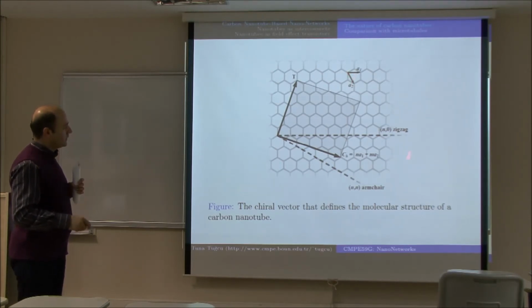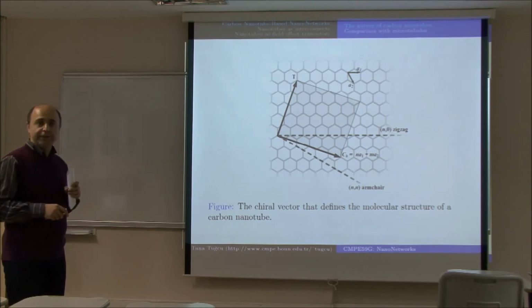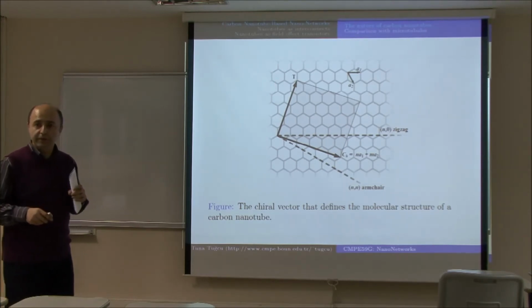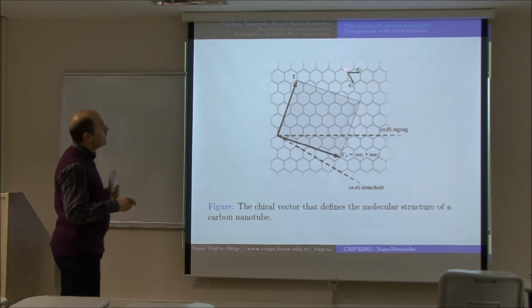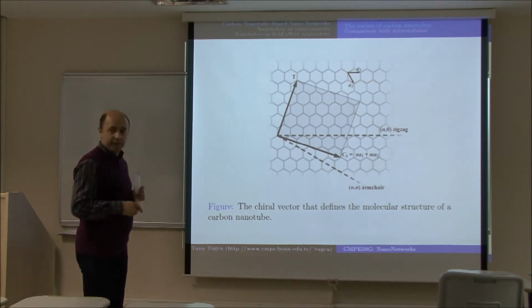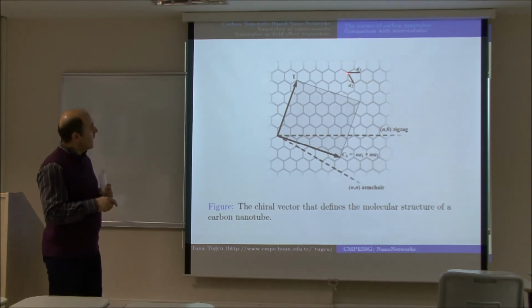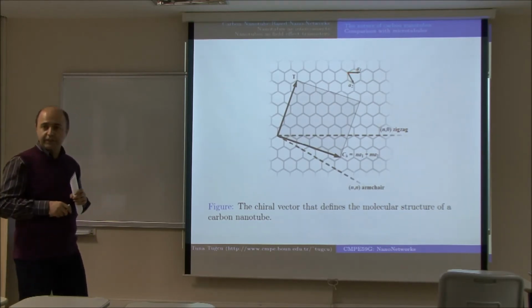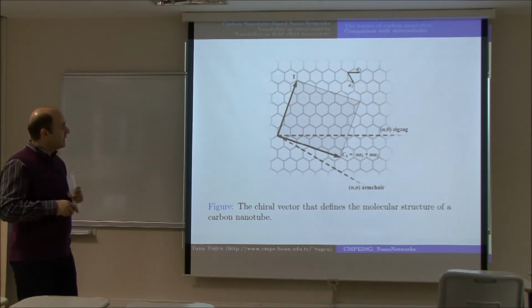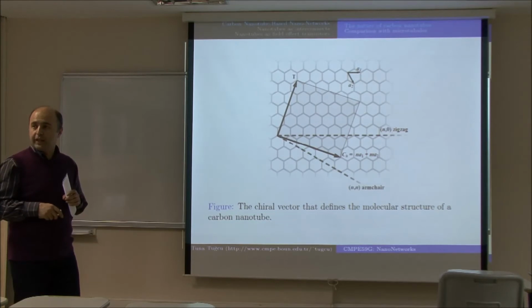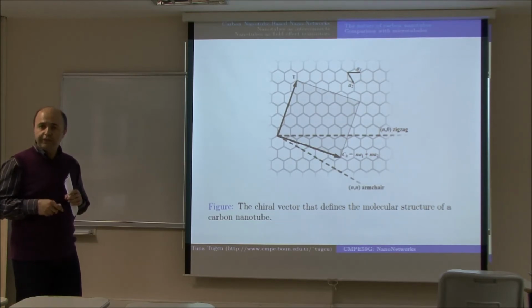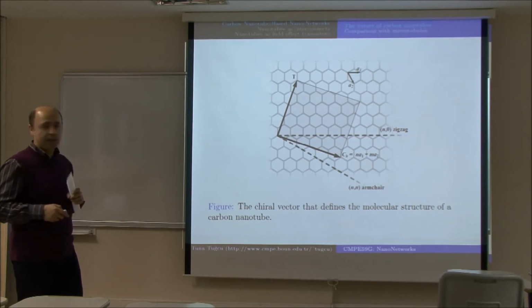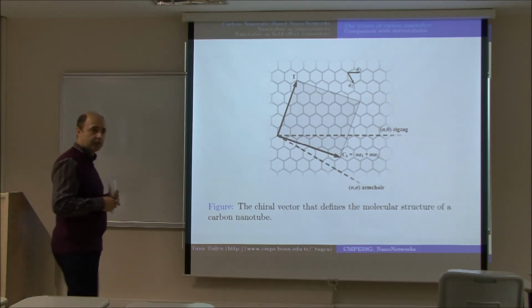Now, see, a1 and a2. The background is our graphene, or carbon nanoribbon at the moment. As you see, there's the hexagonal structure. And a1 and a2 are the unit vectors here. And by putting factors n and m in front of a1 and a2 respectively, you define a vector. Different n and m values will correspond to different vectors.